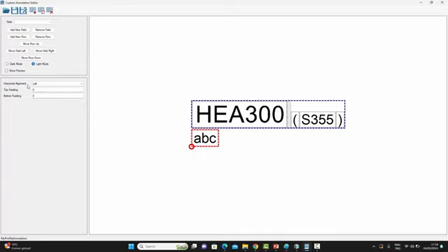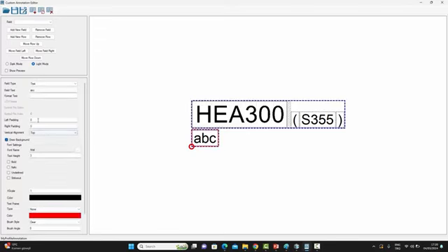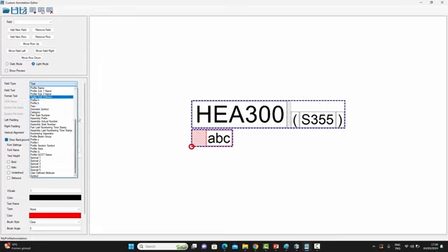And then I get this horizontal alignment. So I can press center, and now whatever I have inside this entire line will be centered along the entire annotation. I can press right if I want. That'll be like that. Or I can bring it to the left once again. If I go inside the field, then once again I have my left padding. I can put a padding of 4 spaces at the beginning, or I can put a padding of 4 spaces at the right. It can be a text, like I said. It can be other things besides a text. If I want, I can choose another field. For example, I can say, give me the object, for example, part actual number.